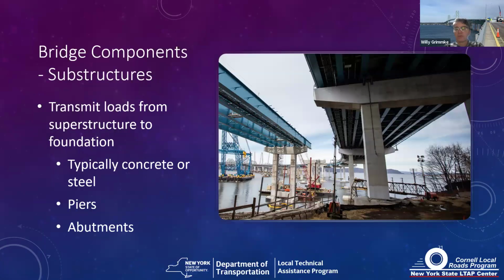Substructure components. So these are the elements that support the superstructure and transmit the loads from those superstructure elements. In this photo, it's plate girders, and they transmit the loads from the plate girders down to the foundation elements.